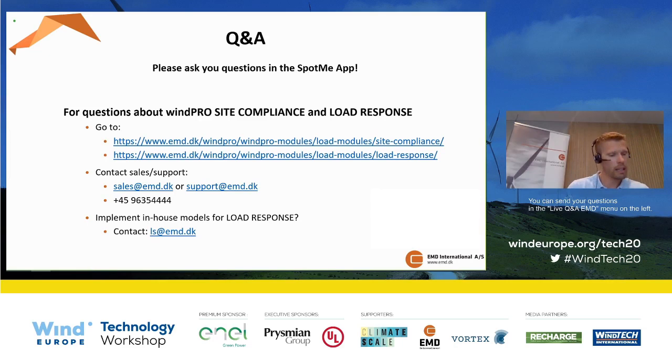And there's a question here whether it's possible to design curtailments with the tool. And yes, it is possible to take into account curtailments in the load calculation. It does not do an optimization for you right now. So if you have a curtailment scheme, you can implement it in your wind turbine objects, and it can be included in the calculation. You just need to check the box curtailments, which is next to the checkbox for load response. Let's see, are there any more questions?